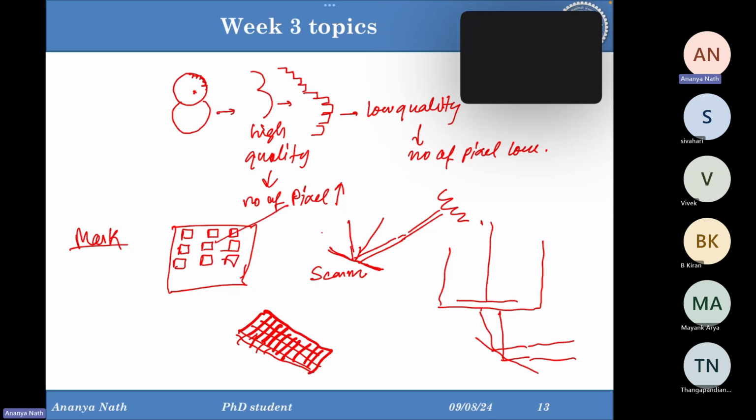When the light is falling over these mirrors, they can get tilted. This is the first position, they can move like this, or like this. They can just tilt a little bit, moving on their own axis, so that they can reflect the light and project it onto the substrate. Only those mirrors will move and project the light on the substrate where the object needs to be solidified.